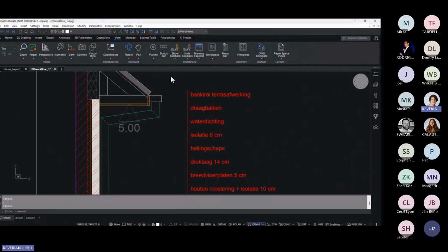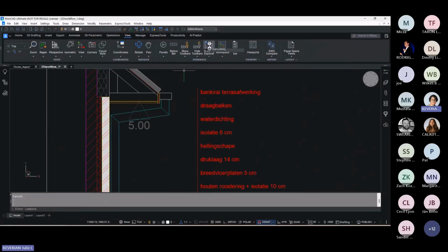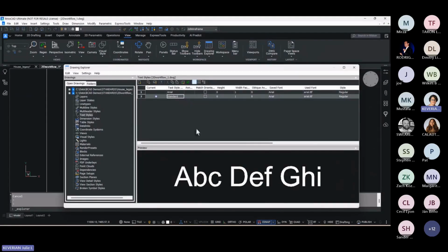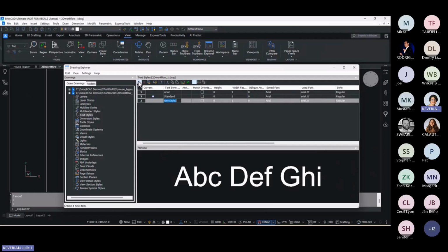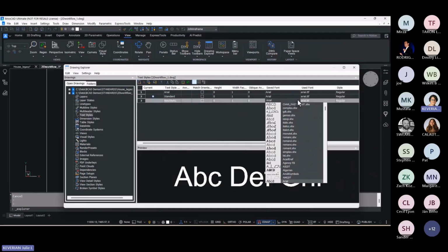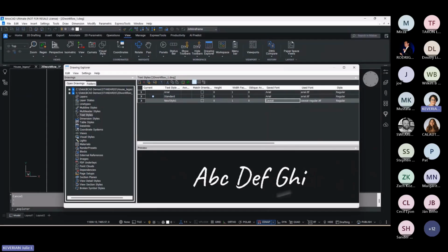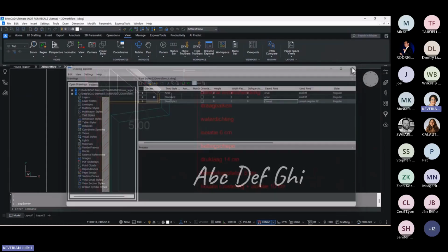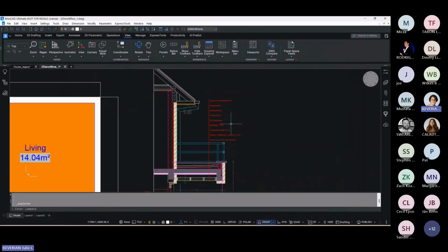So how do you avoid this? Well, create new styles for any customizations. Make all the changes in those new styles. Leave the default standard styles untouched. Now, if they've already been changed, you may need to restore the original quote standard style by replacing it again in your drawing, and then reassign text or dimensions or whatever to the new custom style.